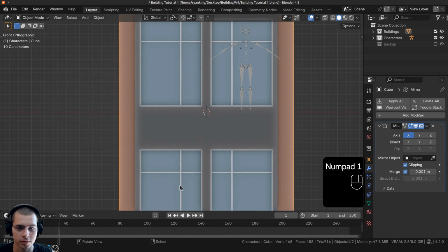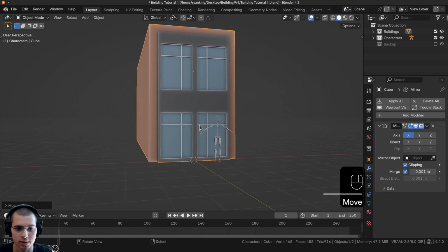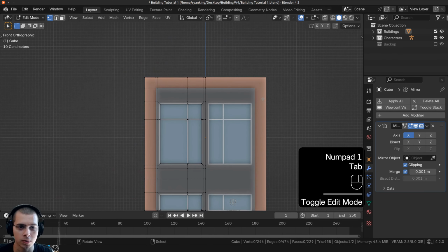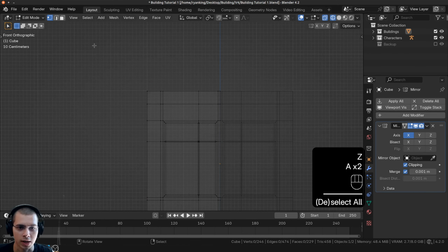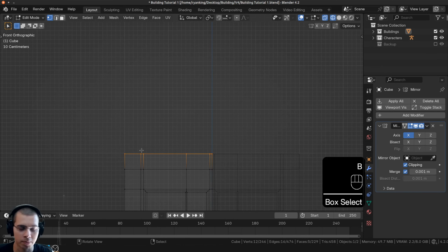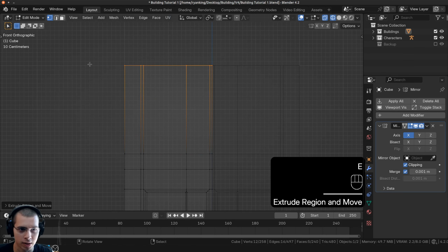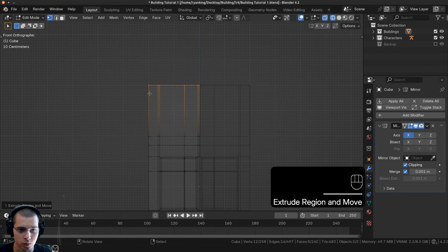So now let's go to front view, and we want to move this up so it's resting on the x-axis, just like that. So we'll go to front view, and we'll go into edit mode, and we'll go into wireframe, and I want to just box select the top vertices, and we want to extrude this part up by another 2 grids. So I'll extrude it, we'll bring it up on the z-axis, and bring it up by 2 Blender grids there, so 1, 2.